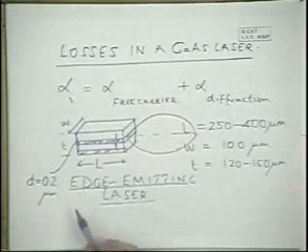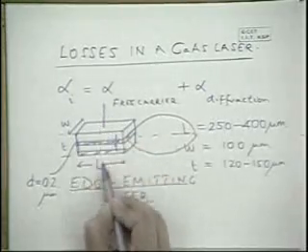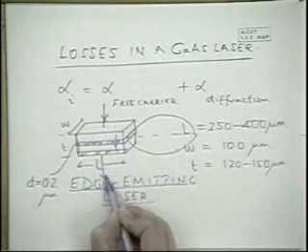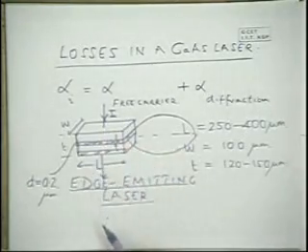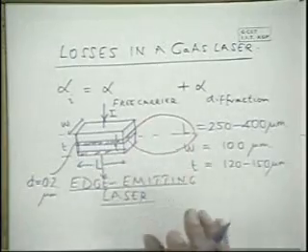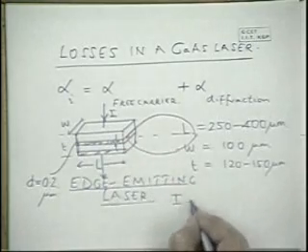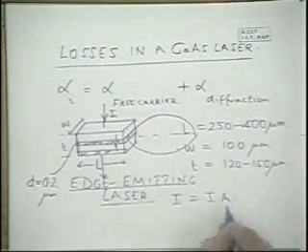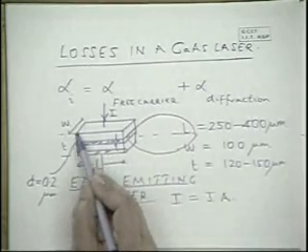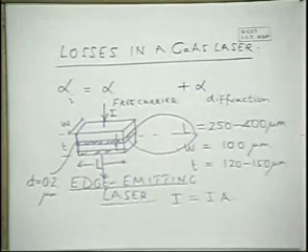So the active layer thickness can be very small. Now, where does the current flow? The current comes in there and it exits there. You want to avoid the effect of the surfaces, and you want to have a high current density, and I is J into A. What is the area? The area is this W into L, which is fairly large.